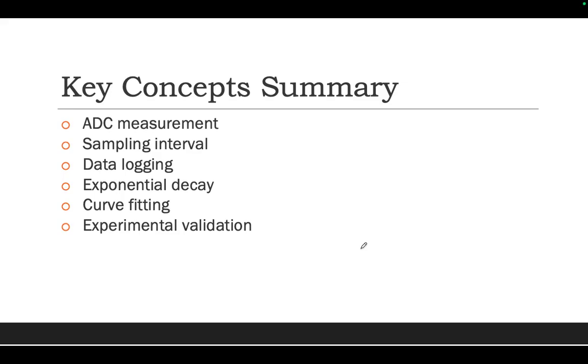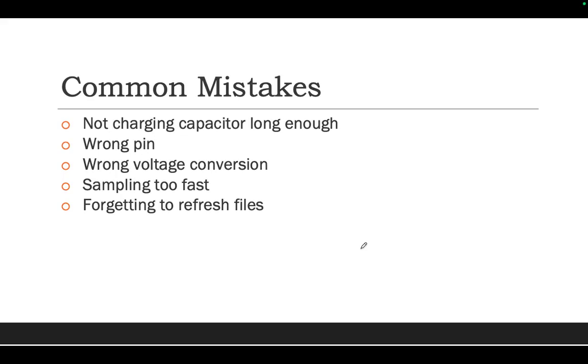Experimental validation. This is the lab for today. Here are some common mistakes you need to avoid. Not charging the capacitor long enough, because if you don't charge it long enough, the circuit may show some strange effects.